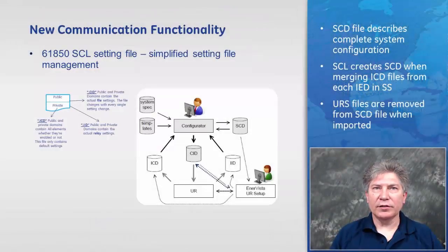The SCD file, the System Configuration Description file, describes the complete system configuration, including the single line diagram, all the IEDs and their information models, and the data flow between the IEDs. It is intended for configuration exchange from the System Configurator tool to each one of the IED configurator tools.